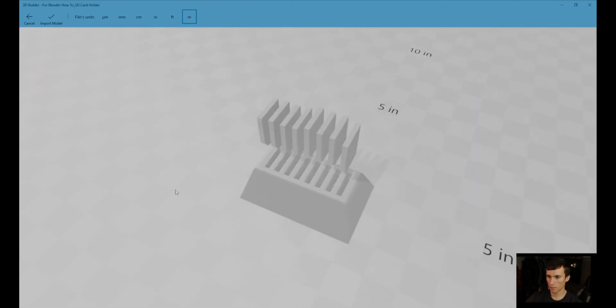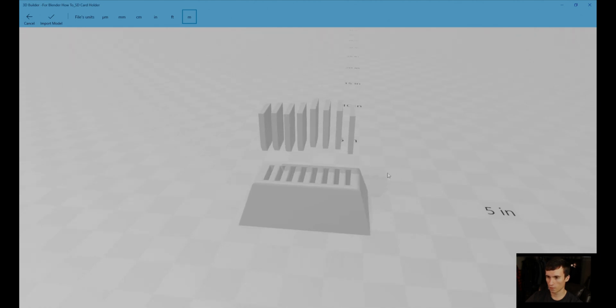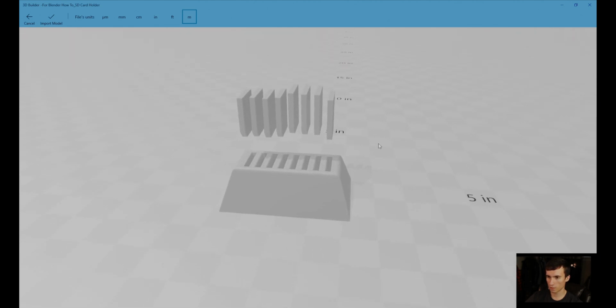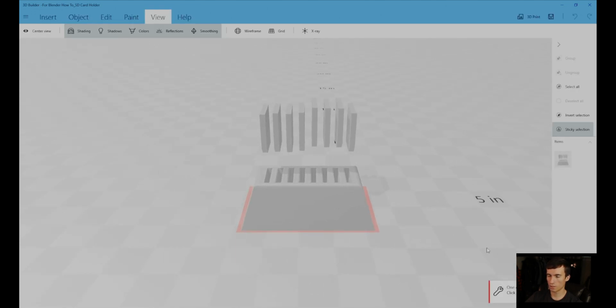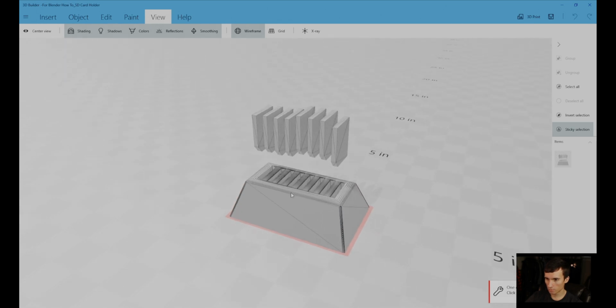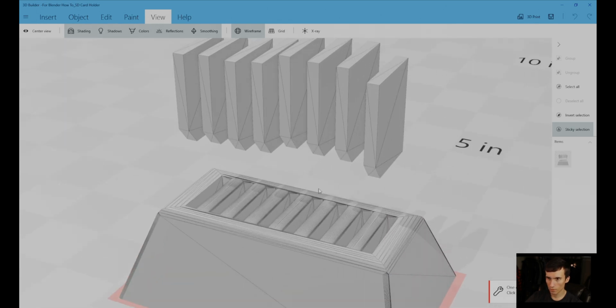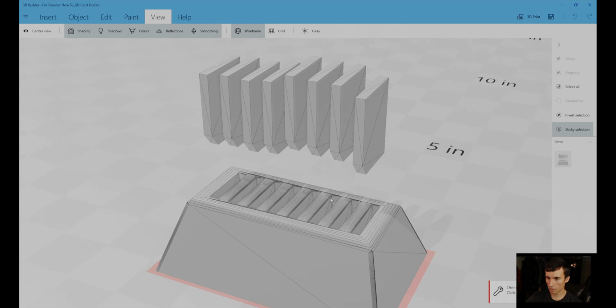Left click and drag to move the view. The right click moves just positionally, and the center doesn't do anything. Alright, so import, and it found some issues with the geometry or with the wireframe. And I mean, if you want to see the wireframe, there's the wireframe. Also, middle click and drag zooms it. Anyway, I'm going to click this button, which automatically runs an algorithm that fixes all the wireframe geometry.